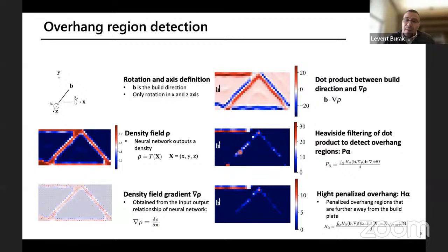So in additive manufacturing, you can create slanted builds that are not going 90 degrees perpendicular, but can build upon the previous layer while moving to the side. So this is called the build angle. In our case, we're using a 60-degree build angle, meaning that as long as you're within that 60-degree angle, you will not need support structure to support that part of the net shape.